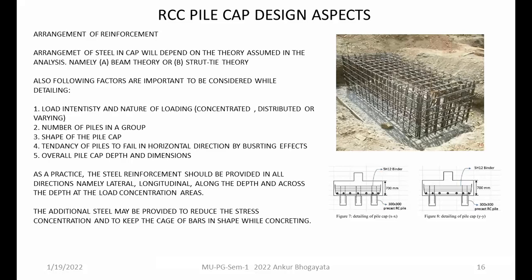And finally, here you can see, I would not advise you to carry on with this practice. Like you can see here that due to the more number of piles, we have provided steel in the bottom only, and the top is not provided with the steel. That's not an advisable provision, because when the load concentration increases with the construction of the structure or superstructure, there are chances of receiving cracks at this junction.